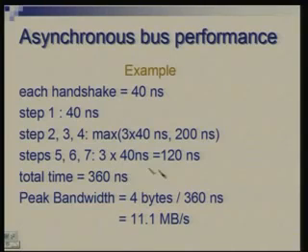What this example is indicating is that the synchronous bus is slightly faster, which indeed is the case. Of course, if instead of 40 we take 30, things may be different, but the relative values are quite realistic, in the sense that synchronous buses are generally faster, because you are not waiting for sensing the signals and acknowledging them. You make assumptions and simply go by that.